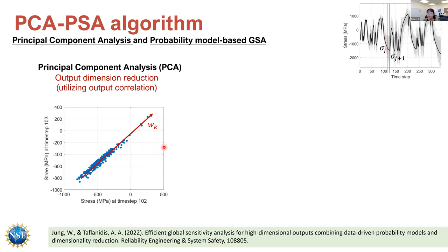This is intuitive when we have a low dimensional data set, but when we have a high dimensional data set, it's hard to imagine this subspace of the larger dimensions. So the perspective I like to introduce to interpret this high dimensional PCA is to draw an analogy to conventional methods such as Fourier transform or modal analysis.